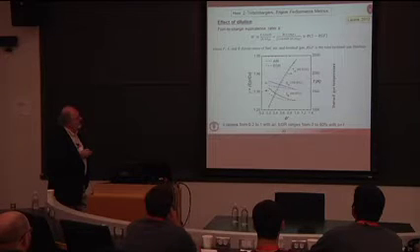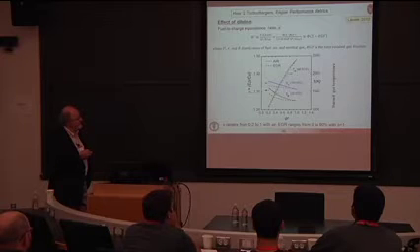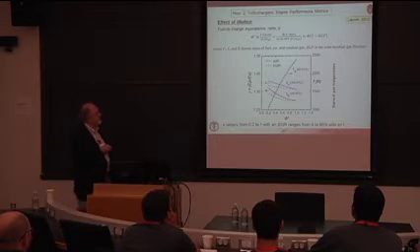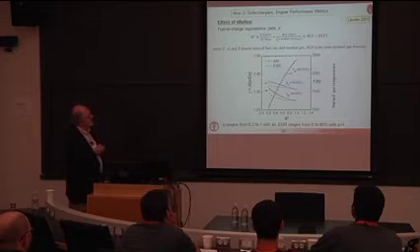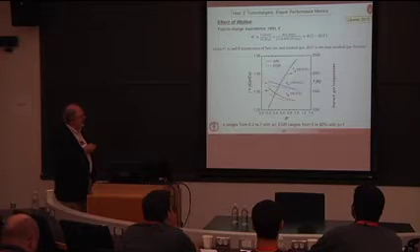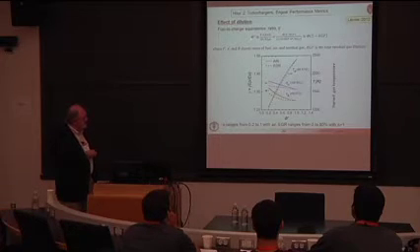So in this case, the equivalence ratio can be unity. In other words, you can have stoichiometric combustion. However, because of the recirculated gas fraction or residual gas fraction, which can be up to 80%, you can have an effective lean mixture. The fuel to charge equivalence ratio can be of the order of 0.2.